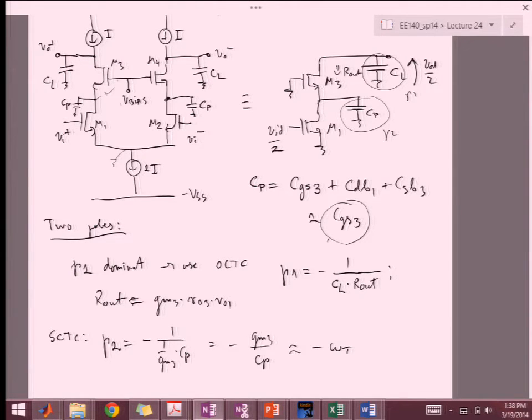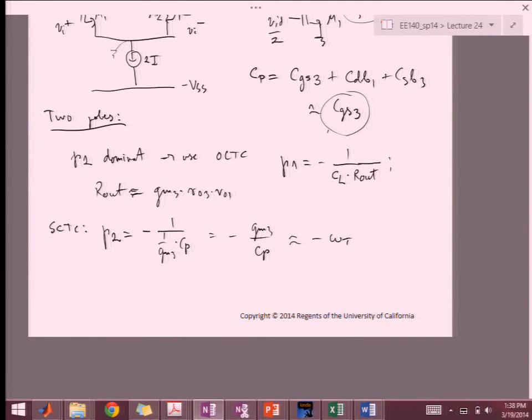So it sort of signifies how fast a signal can go through the transistor and still do something. Okay, so this sort of shows you what the benefit of the cascode is: it introduces a second pole, but the second pole is very far away. So potentially, in the feedback configuration, you can extend the closed loop feedback all the way to omega 2.